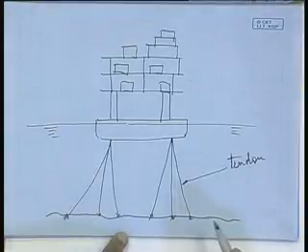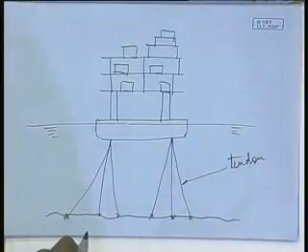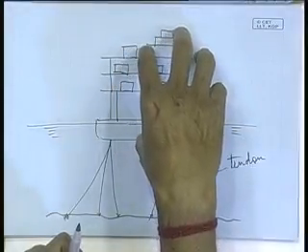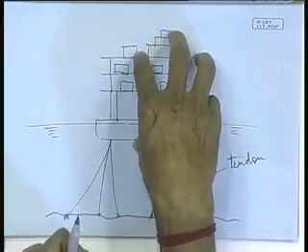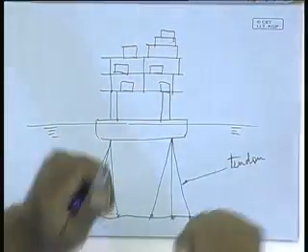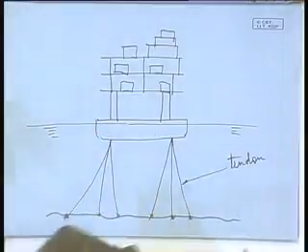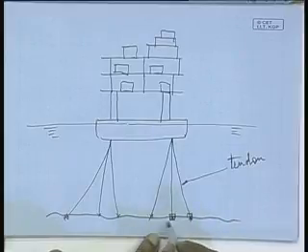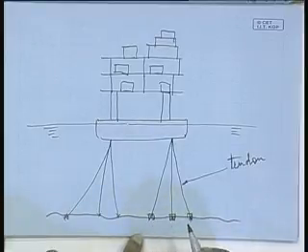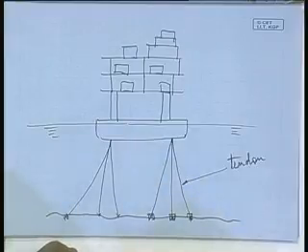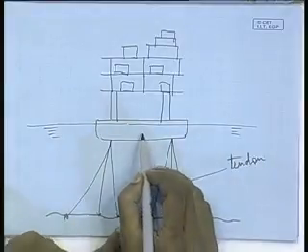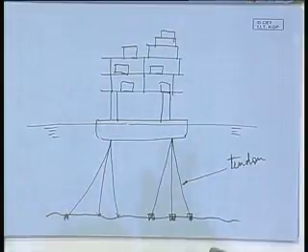So what is done is, as if you tie the entire offshore platform, the floating platform, with ropes down at the seabed. That means at the seabed you have the necessary tying arrangement, or so to say hooks grouted in the seabed. To that you tie it, right? And then this will have a positive buoyancy.